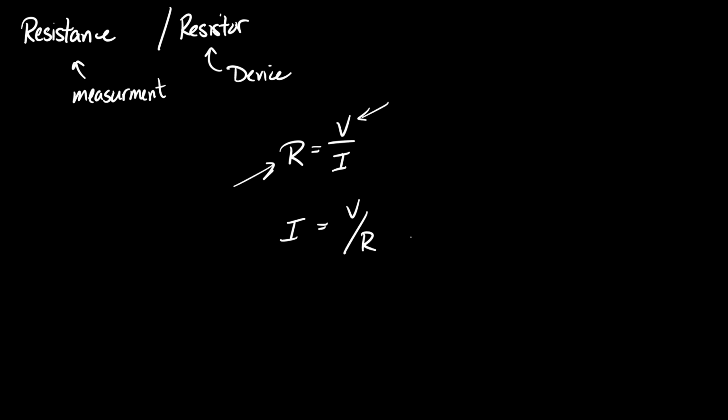But since resistance is measured as how much resistance there is to the flow of charge, as opposed to the opposite of the word, which would be conductance. Resistance and conductance are inverses of each other. Conductance would tell you how easily charge passes through a material. So resistance is the reverse of that, which is how hard you have to push to get something to go through a material. Higher resistance, less current for the same applied voltage.